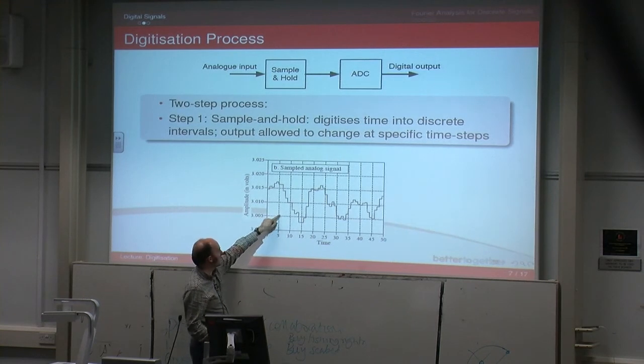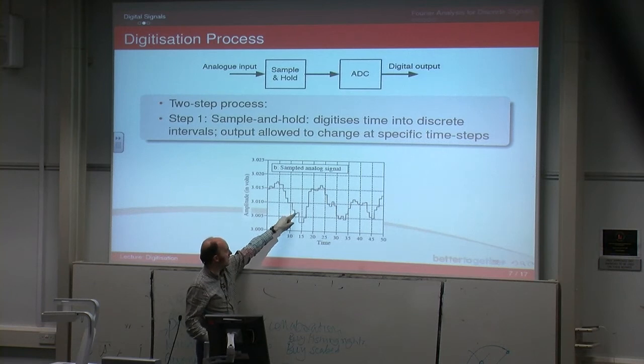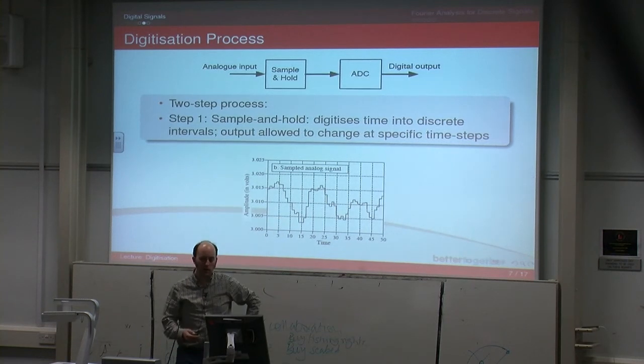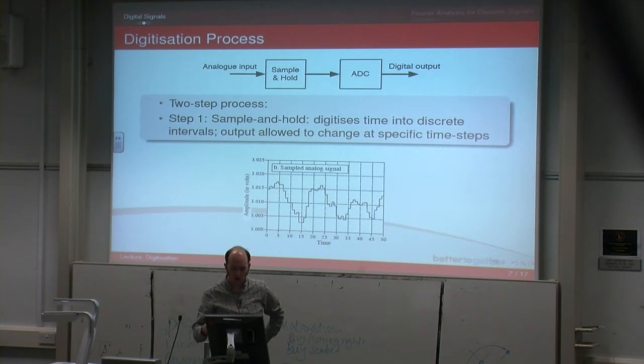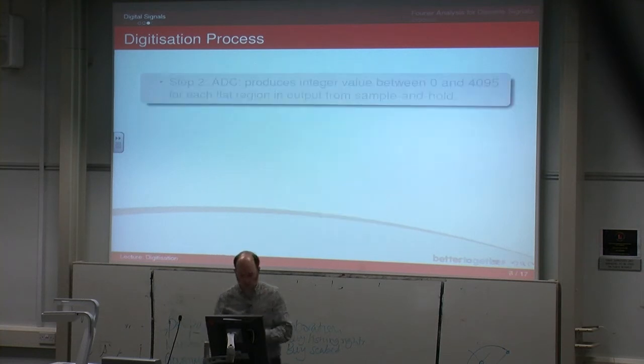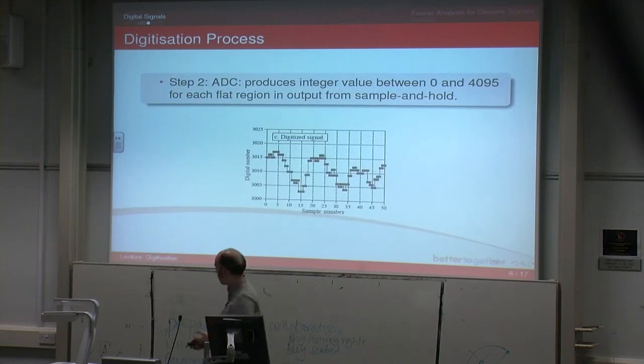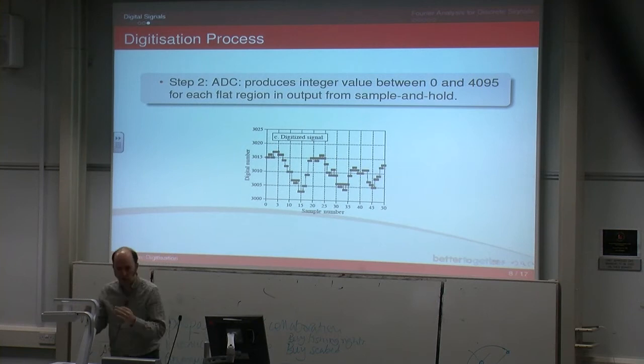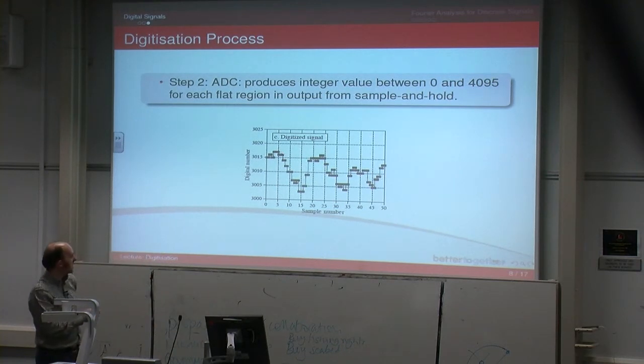So if you've got a value that's 3.0055, we'll say, or whatever, you're halfway between 2 points. Obviously, that doesn't relate to one of the specific integer values. And so you have a situation where your data gets slightly shifted. So that's what happens, the output from the ADC is you have a bunch of values that are associated with each of those step values, the step signals.